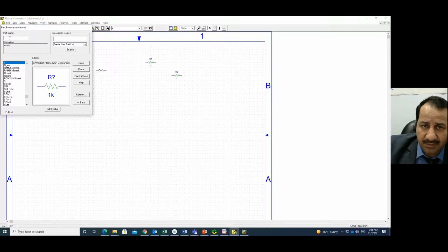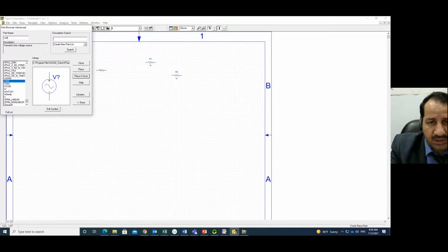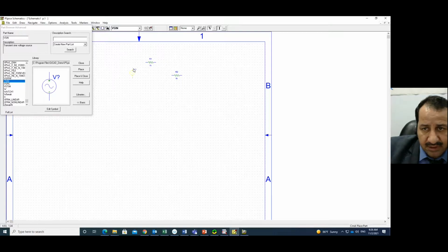Now I go back here. I also need a supply. So I know the item. By the way, you may write V and start searching. So I know that the supply is the V sign. I will take it. Place. I will put it here. You see, this is the supply.